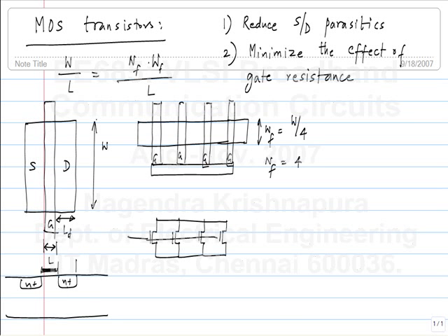And there is a capacitance of the bottom of this junction, and there is a capacitance to the sides. These are modeled separately because again the depth is not in your control, but the area is in your control. So for instance, you can extend it in this dimension, horizontally, but you can't do anything to the vertical dimension. Like everything else, the capacitance is modeled using 2 parameters. One is Cj, which is the capacitance of this per unit area.